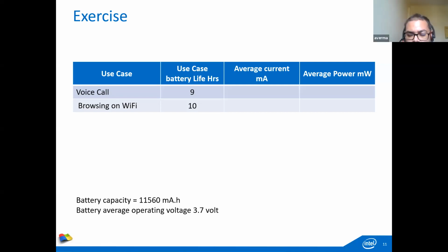It's not 1 volt. It depends on the technology. For example, CMOS can be different, TTL can be different. Most of the CMOS technology right now, the operating voltage could be around 1.2 volt. So it's not that it operates at a specific voltage of 1.5 volt or something like that. Also, it depends on what frequency. So there are many constraints which dominate what the voltage will be. Certainly not in the 12 volt range nowadays.